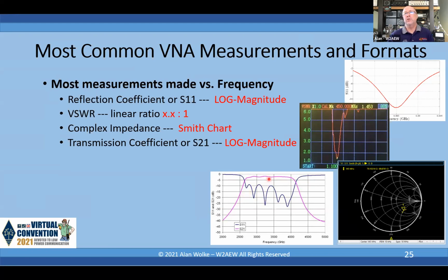So it's going to pass the signal right through. But the way that this is actually being a bandpass filter is that for signals outside of the passband characteristic here and here, we can see that S11 is near 0 dB, which means it's reflecting all the signal back off of the port, back towards the source. That's why it's being a filter. It's rejecting the signal, not letting it through. It's not absorbing it. It's just sending it back where it came from. Okay, that's what that means.